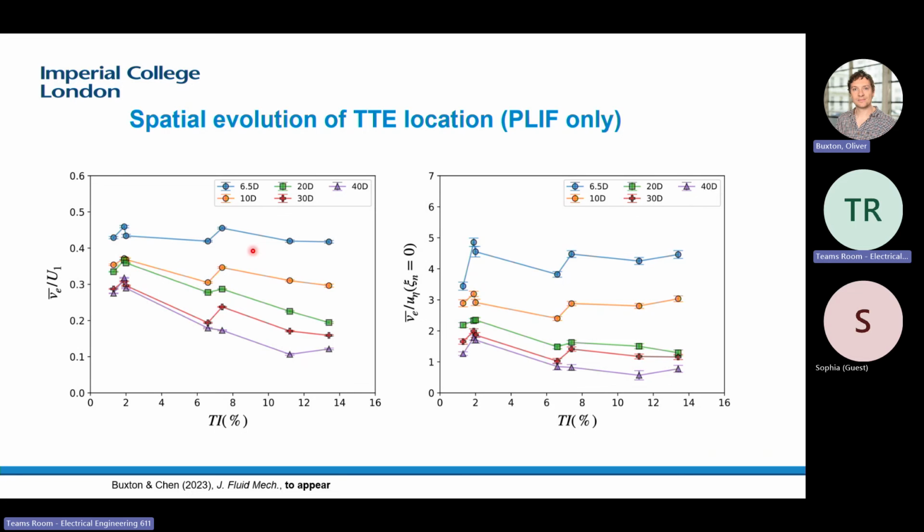Now, our results suggest that free stream turbulence enhances the large-scale process, but diminishes the small-scale process. And in the near wake, the large-scale process is important, which is why, as you can see, this is my non-turbulent flow.